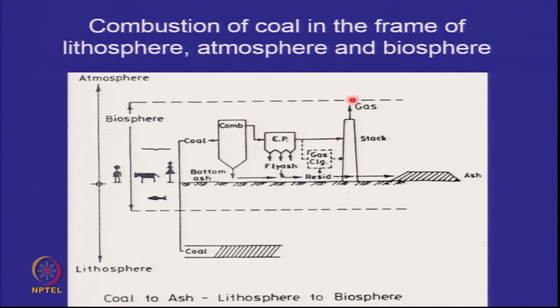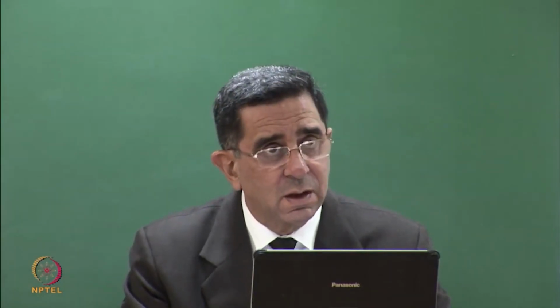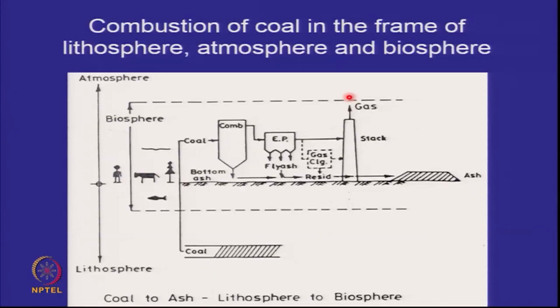To prevent this air pollution, we normally install what is called electrostatic precipitators. Now we will not go into what electrostatic precipitators are, but these are nothing but very large plates which prevent these fine particles from going out with the hot gases. They attract these fine particles to their surface because of electrostatic charge, and therefore you get clean gases coming out, no smoky look, and all this is collected on the plates which are occasionally vibrated, and it falls down into the bags below and comes out as fly ash.